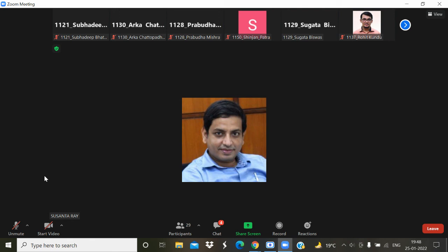So the range which is given in the book is okay for pre-design, freehand design, but when the frame size is given, it would not be possible every time to maintain that L by tau ratio up to 2. So you can exceed the L by tau ratio beyond 2 also. Okay, no issue in that.